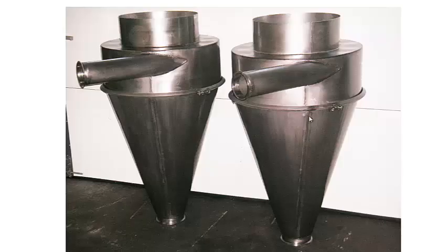And I just want to show you this one too. When I said we would push our branch off, so it wasn't just sitting right on top, that's what's going on in this view here. What I'm looking at specifically is just this branch coming into this round cone. I'm not talking about the cone here, just this round-around intersection right here. This branch, rather than just coming in on center, they bring it far to one side. Actually, they brought it all the way flush to one side, which would start a centrifugal motion. If it was incoming, whether fluids or solids, they would start a spinning action in this.